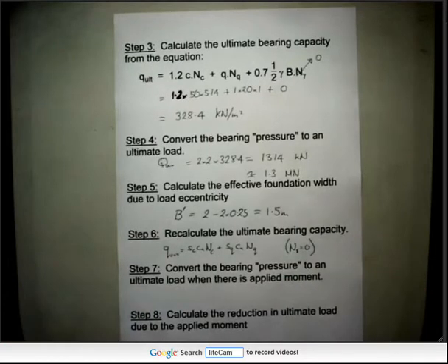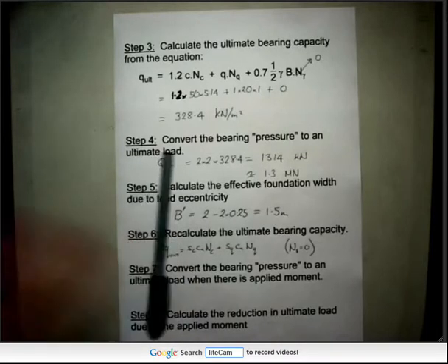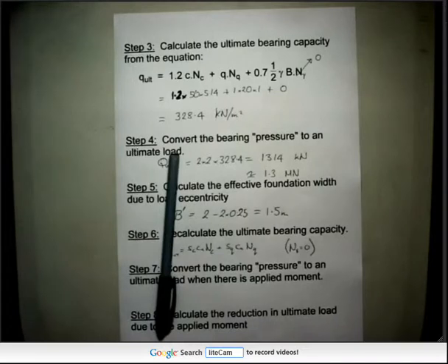Now, what I've done now is just cheat very slightly. I've said when you go from square to slightly rectangular, the shape factor only changes a little bit. After all, when it goes all the way from square all the way to a strip footing, which is an enormously different aspect ratio, it drops from 1.2 down to 1. So going all the way from square to a strip footing, it drops by 0.2.